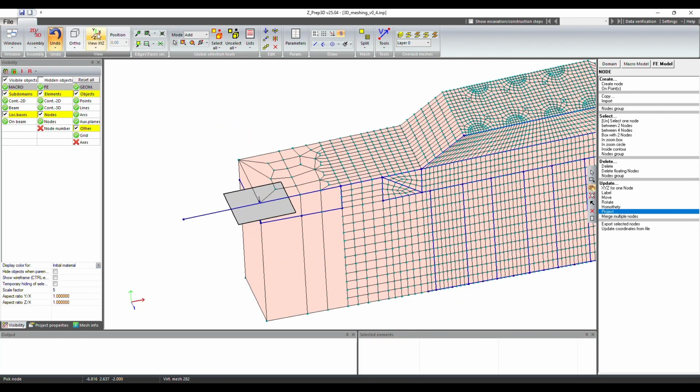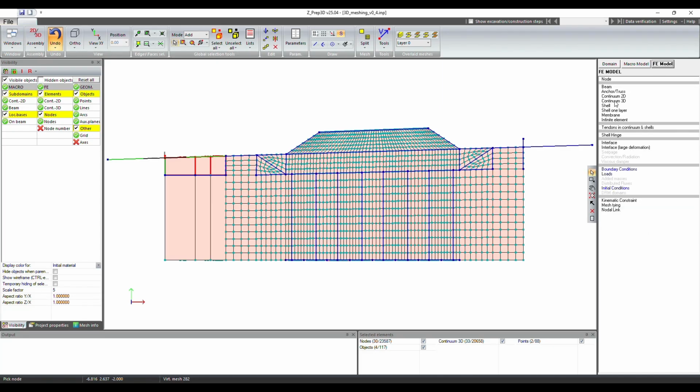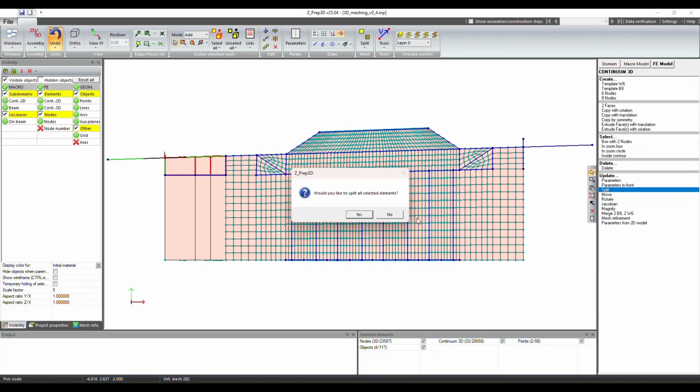We need to split the mesh. So up here we have a 4-element split. I already know from experience that this direction will be the third edge shown here because the elements were created by vertical extrusion. So I can directly specify the edge to be split.